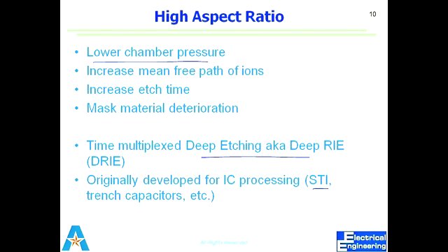Okay, actually, when you introduce the plasma, there are energetic ions. So the higher the energy, the higher the mean free path would be. Similarly, the chamber pressure also affects the mean free path. The mean free path depends upon two things. One, what is the energy of those ions? Secondly, what is the environment like? If the environment is putting up some pressure, of course they cannot move freely. If they are not experiencing some external force, they can move freely. So by increasing the energy, you can supply a higher-power plasma, or you can decrease the chamber pressure. These are the two things that you can control.